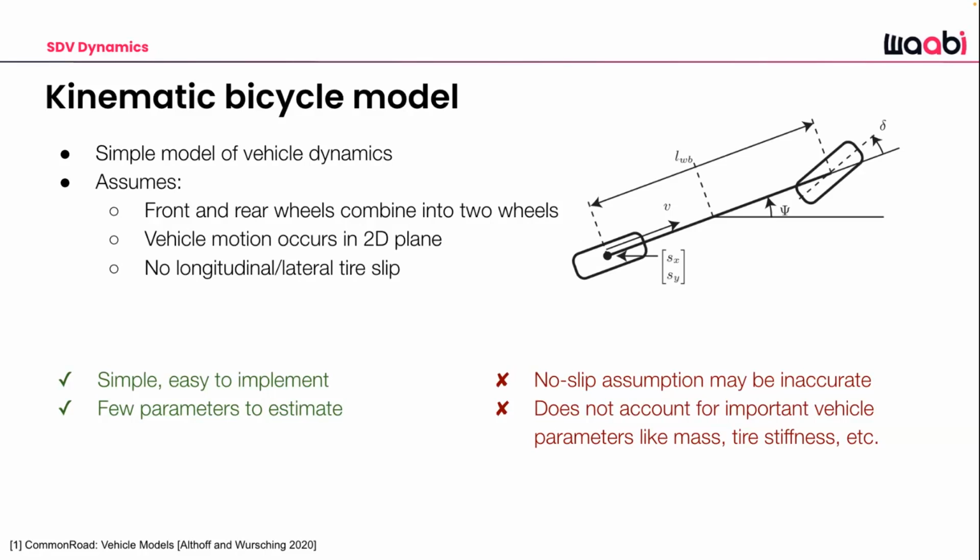And yeah, these are very simple, easy models, and they don't fully account for all the things you might think need to be modeled for vehicle dynamics. For example, there might be tire slip. If you have environmental conditions like wet roads, there are more changes in friction that you need to account for in your vehicle dynamics that don't typically get modeled in a kinematics model.